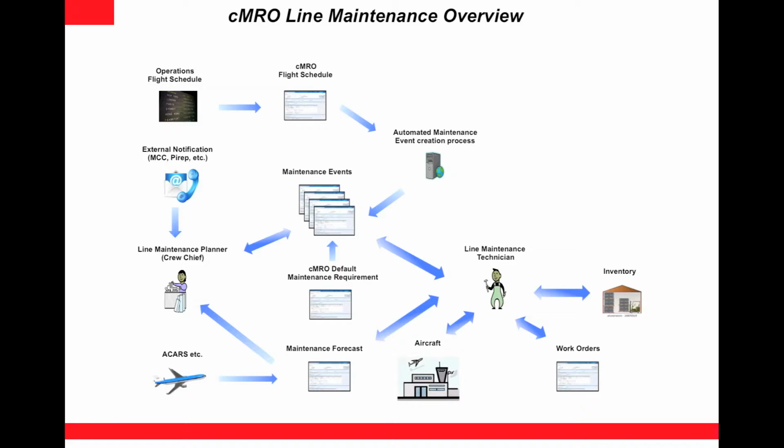In case of non-routine write-ups or other assigned tasks that are not cleared as part of the ongoing visit and do not affect airworthiness, such as MEL items, the technician can initiate a deferral process supported by an approval workflow which will automatically add the deferred tasks to the maintenance forecast for future consideration. Even with all these options, the workbench is designed in such a way that it supports both the simple tasks as well as the more complex tasks in the most efficient manner with as little navigation and data entry as necessary.